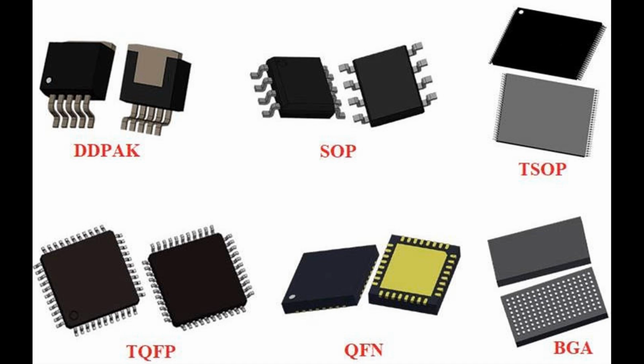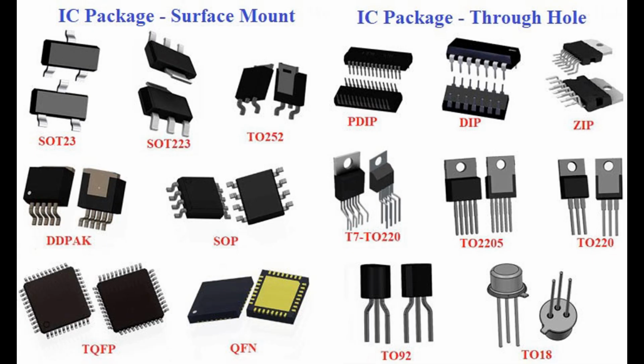3. Inter-integrated circuit, I2C. Function: I2C is a multi-master, multi-slave synchronous serial communication protocol for connecting various digital devices. Used for communication between components like sensors, EEPROMs, and other peripherals. IC type: I2C interfaces are integrated into microcontrollers, and standalone I2C interface ICs are available.